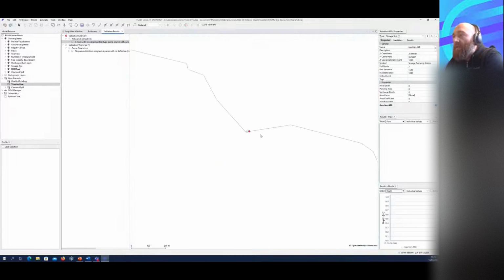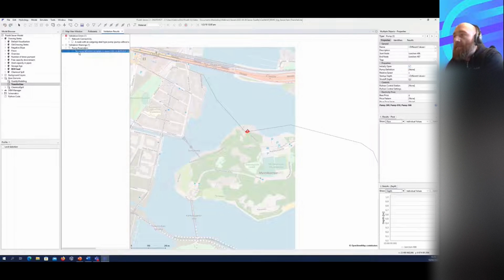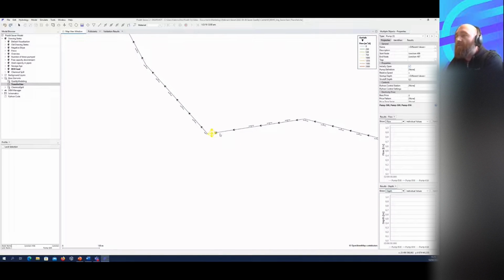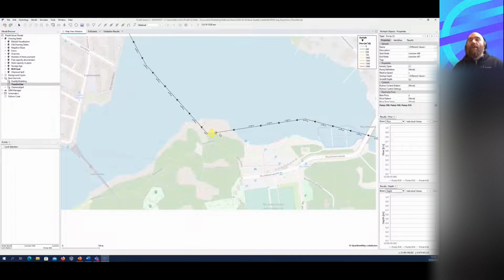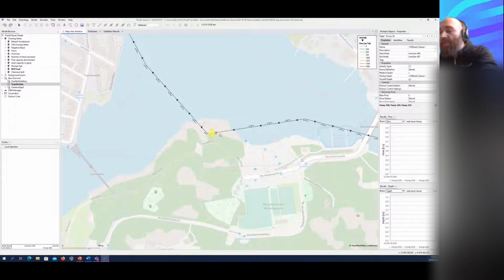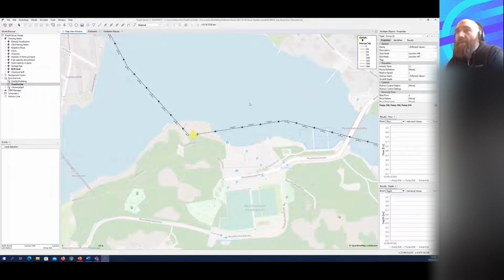In this scenario, there are a few pipelines, a few pumps missing their curves. But that's not a problem. If you model a lot of sewer networks, you encounter that some of the pumps don't have their pump curves because they might be such old pumps and nobody knows what the type is or anything. So sometimes you need to generate some pump curves for these.